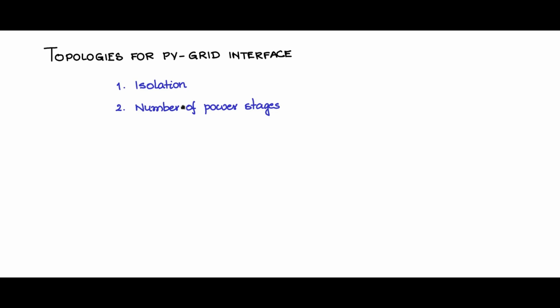There can be another converter for doing the unfolding. So you will see that there are some topologies which use 2 or 3 converter stages, some topologies which will use just one power converter stage. So it has an impact on the efficiency of the whole system. So you will see in the literature topologies based on the number of power stages too.